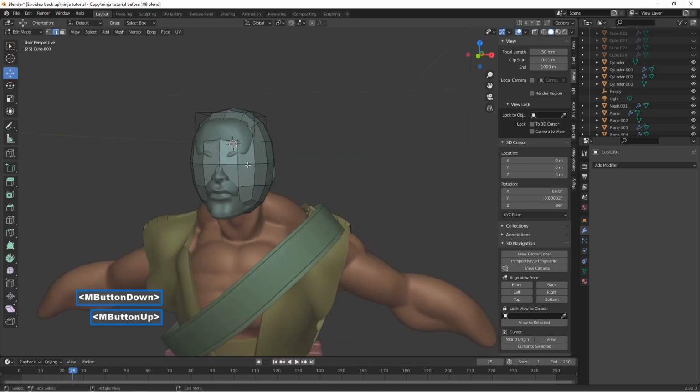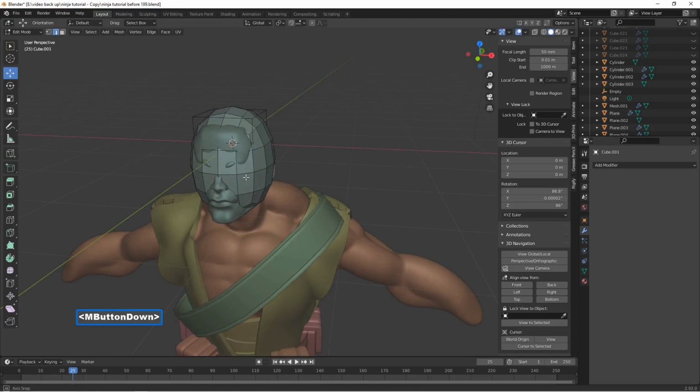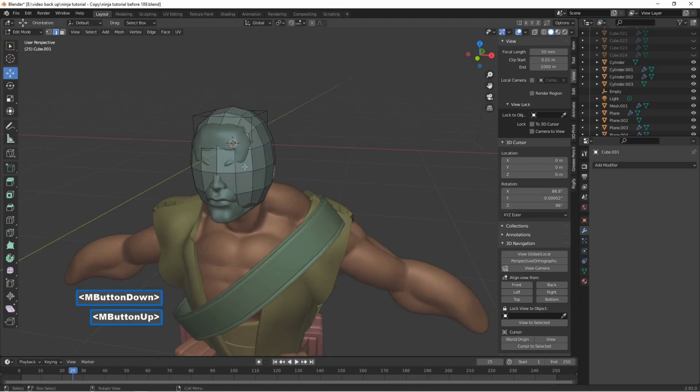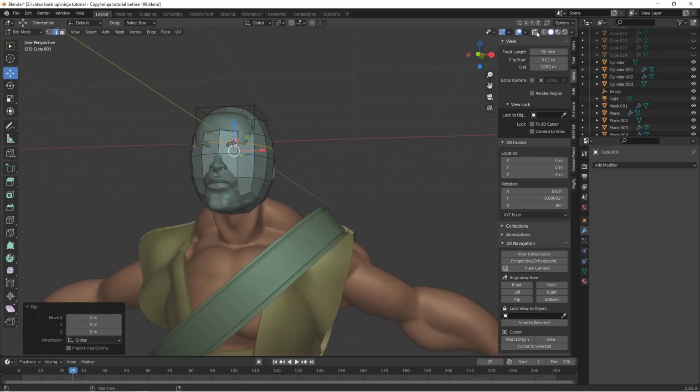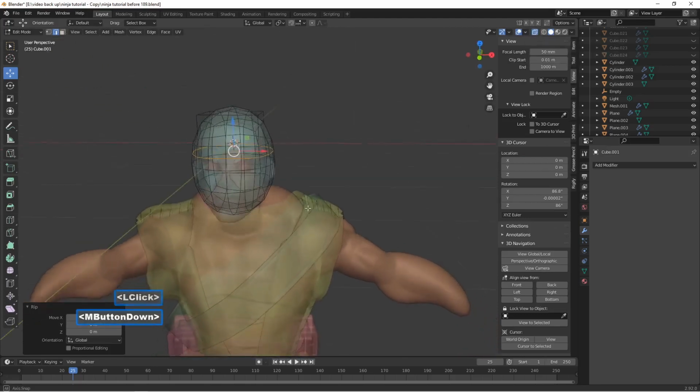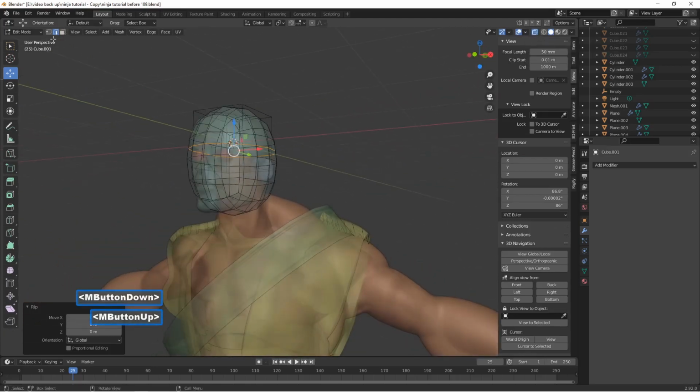And then what we're going to do here is I'm going to hold Control, press R to put a loop cut here. I'm going to hold Alt, select that loop cut. I'm going to move my mouse underneath the loop cut, press V so I can rip this, right? Now I'm going to turn back on X-ray mode. So I can see, I'm going to go to the upper left, go to vertex select.